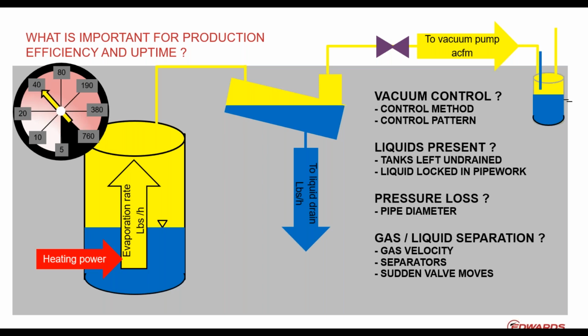So it's just as a last idea before we close this. If you have a vacuum pump running with a closed inlet, just waiting for the process to get right, and let's say it's a 4 or 6 inch valve, the vacuum pump basically pulls down to ultimate pressure, whatever that is, depending on the vacuum principle. And we want to go there. We're going to go through that in webinar 3.